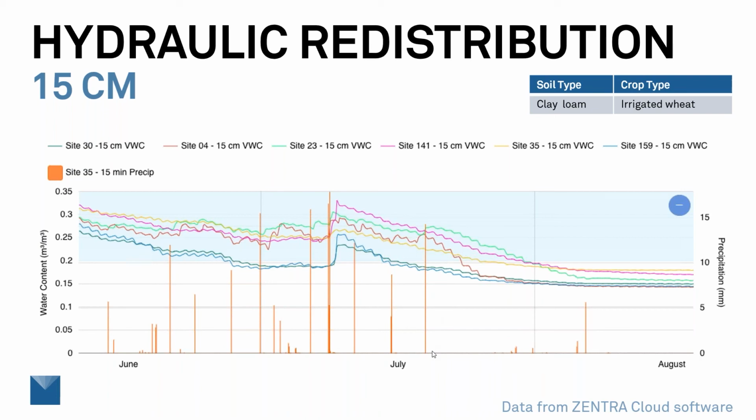And we actually turned the irrigation system off in late July. These are a couple of precipitation events that happened. And we see this interesting diurnal pattern in the data. And if we're sitting at 15 centimeters, maybe our first reaction is to say, oh, those are definitely temperature related. But remember, certainly into June and in July, we have a full wheat canopy growing on top that's fully irrigated. So we have a leaf area index of probably 4 to 5 and very little radiation making it down to the soil surface. It's probably unlikely that we're getting much of a temperature change at that depth.